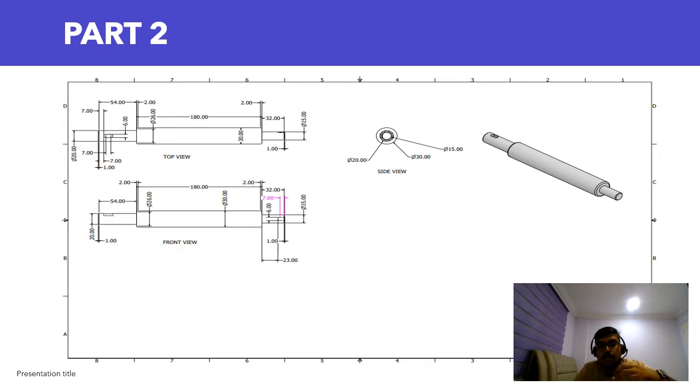I did the same thing on the last piece of the drive shaft, but the difference is I made the indentation go until the end of the piece, which will be attached to the pulley with the pin inserted, and it is 23mm from the starting point. Lastly, I made a chamfer of 1mm on both ends of this part and a fillet of 2mm on both ends of the second piece, which is the middle piece, as you can see.